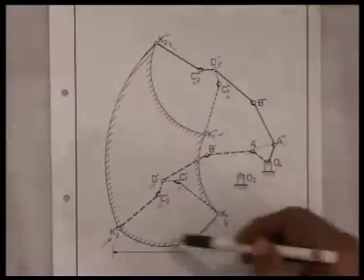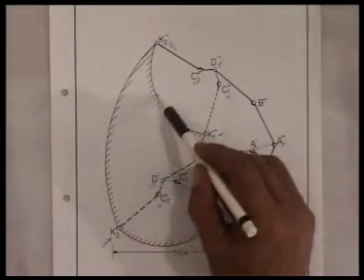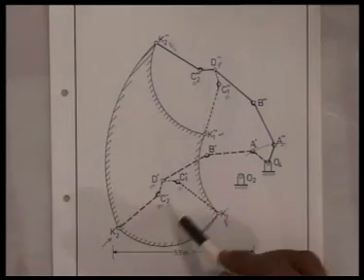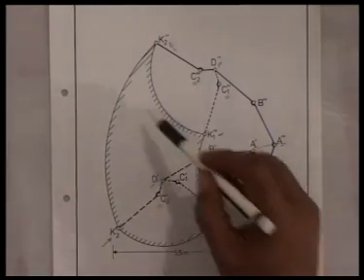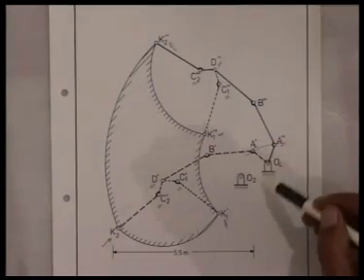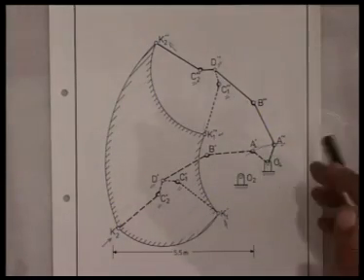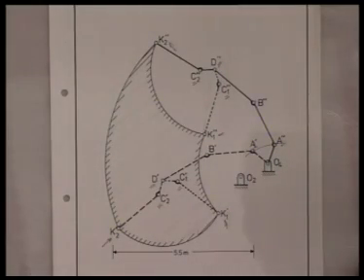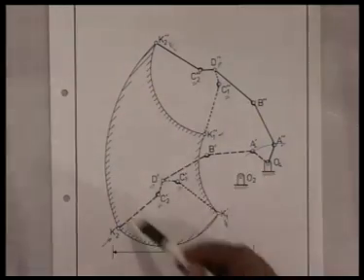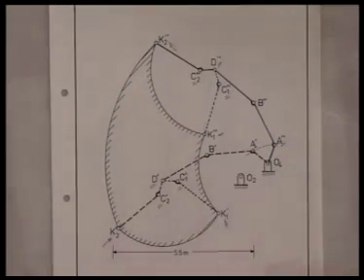So, these four circular arcs determine the region in which the hinge K can lie when the maximum and minimum distances between O2 and A and B and C are utilized by the hydraulic actuators. So, in the full range of operation, the hinge K lies within this region. With this hint, you should be able to complete the problem.